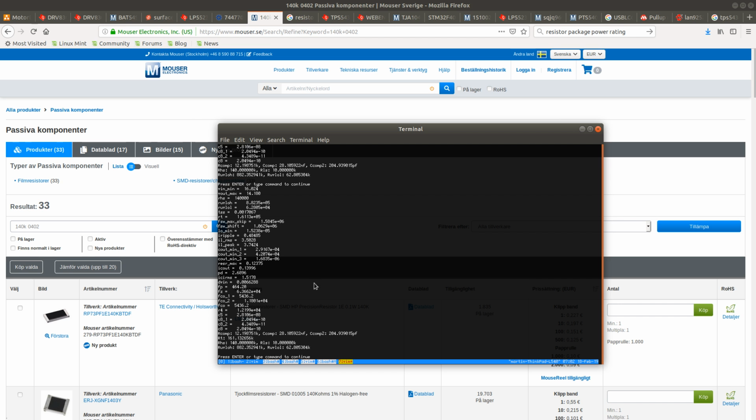We have RT, and we have the absolute maximum switching frequency, 1.58 megahertz. So the switching frequency needs to be lower than these frequencies, and I choose here the same value that they chose for their application, 600 kilohertz.